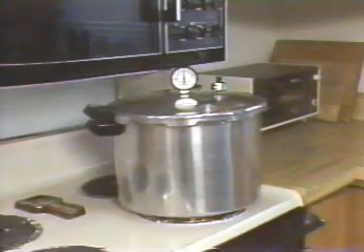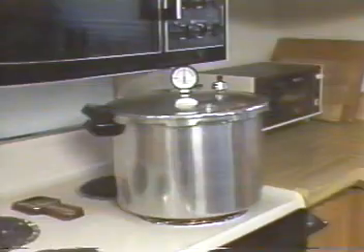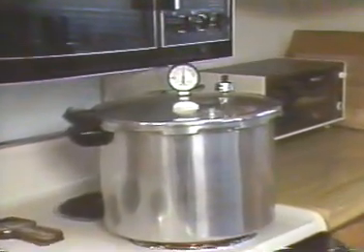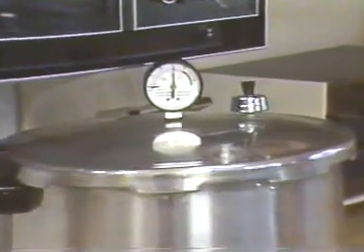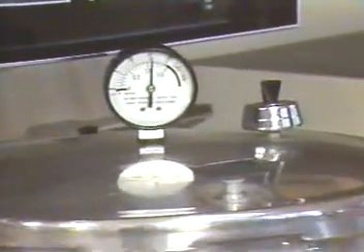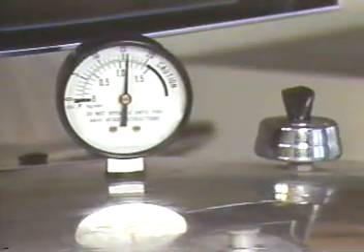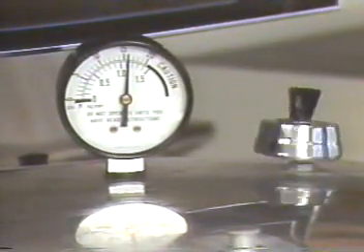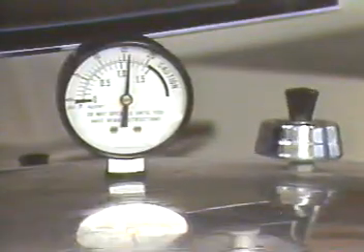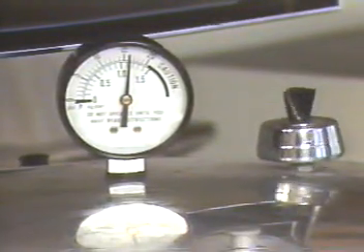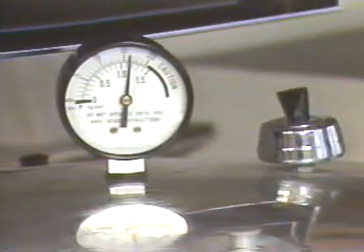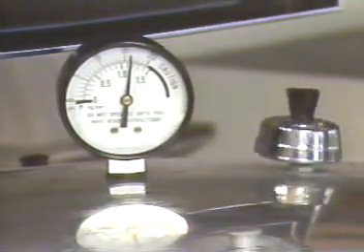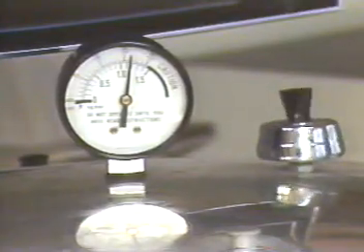For some reactions, another way to make a basic kettle more efficient is to pressurize it. As you know, there's a relationship between the boiling point of a substance and the pressure applied. There is a normal boiling point that corresponds to every pressure. By increasing the pressure, you can raise the boiling point, thereby permitting the water to get hotter. That's how pressure cookers work. They speed up the cooking process by increasing the temperature within the kettle. This is accomplished by increasing the pressure, not the amount of heat applied.